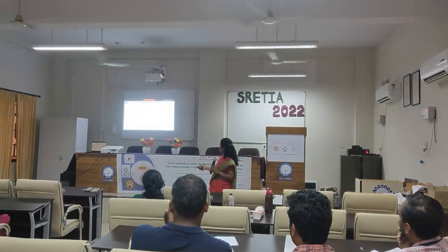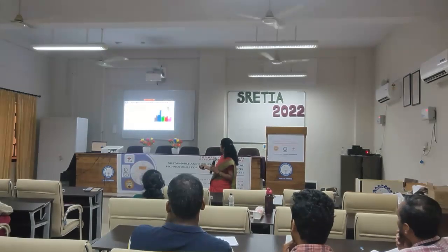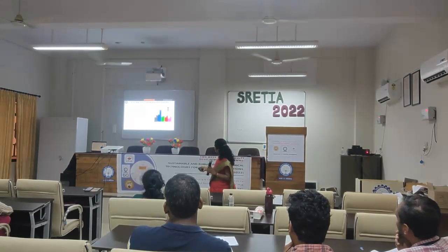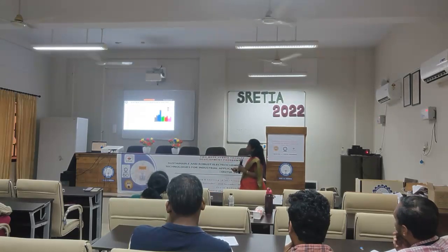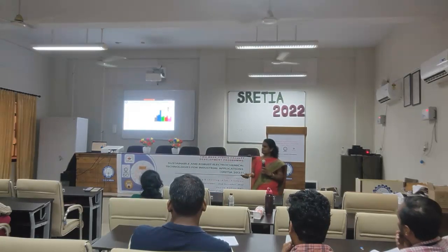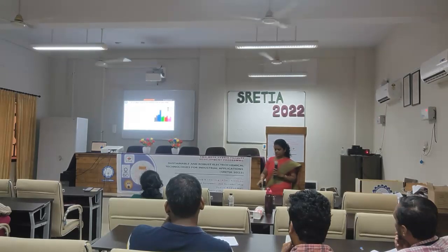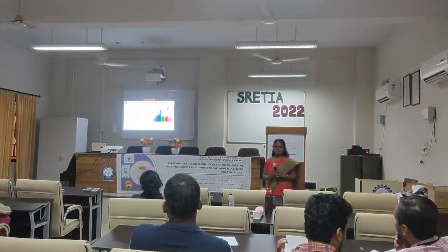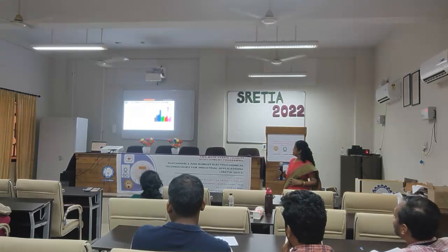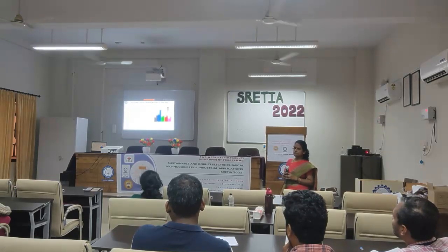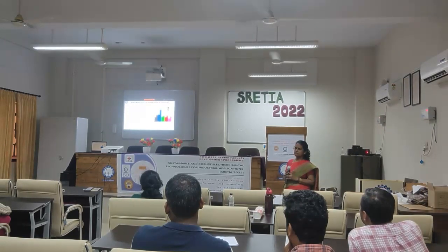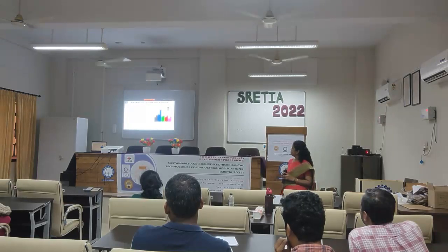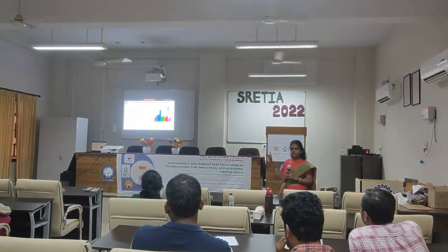For every electrode, with a 1 centimeter electrode gap and a 2 centimeter electrode gap, what is the optimum time? It is written on the top. The black color is aluminium. The first is 1 centimeter inter electrode gap and the second is 2 centimeter. Copper is blue, AC1 is green, AC5 is red and AC10 is magenta. From that you can see the optimum reaction time to get maximum removal of COD.